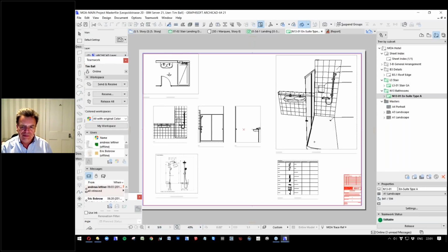And you're starting then to see the benefit of all the 3D modeling you do, because every single part of this, apart from that image there, is all live. So if this is changed on plan, then the internal elevations all update. This 3D document all updates. If you change the data, this updates. So you're getting consistency then of the drawing, your plans, your sections, your elevations, your 3D, and your data right across the whole system.